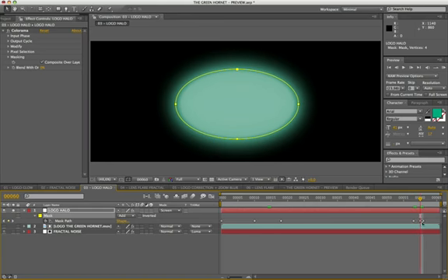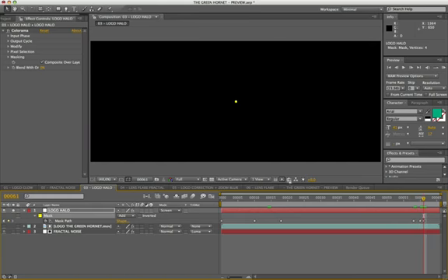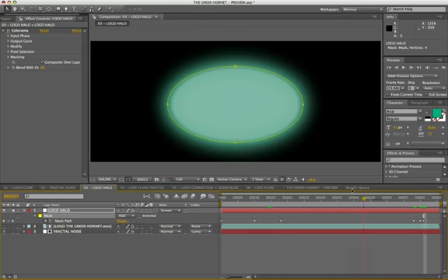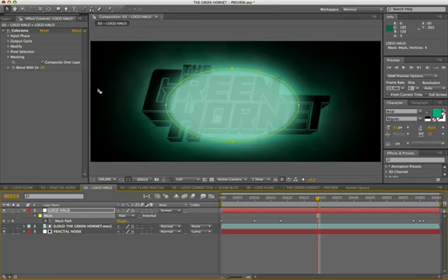It is reduced from frame 60 to 61. It's in add mode. The edges are soft, with the feather value at 185.